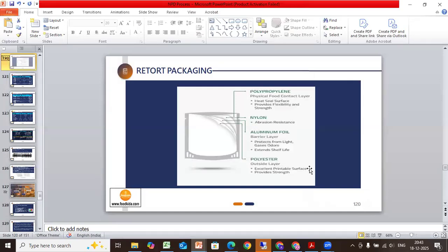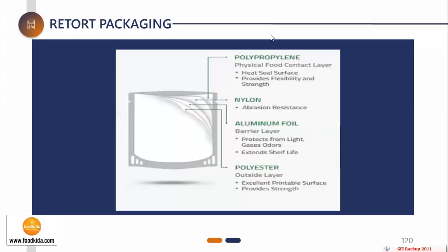Many of our beverages are retort, with 4 layers. See, this is a retort packaging, but see how it is multi-layer. Tetra Pak is also multi-layer. If it is the cardboard Tetra Pak, it will be laminated. Inside they use aluminum foil, or outside also. Cardboard is a very good printing material. You can print on the card paper also. SBS, solid bleached sulfate board, is the packaging material which they use.